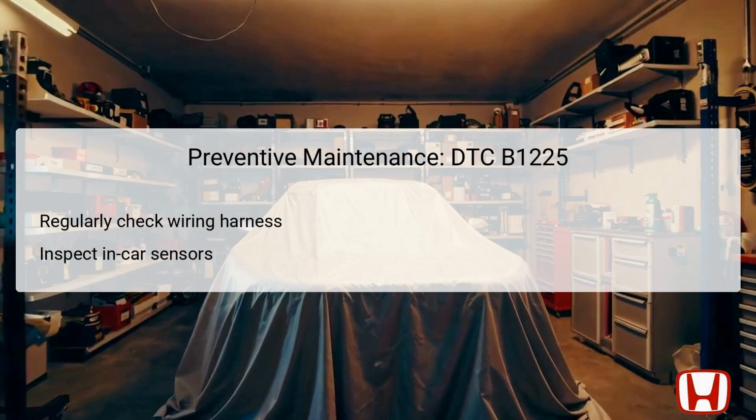Preventive maintenance plays a vital role in avoiding recurrence of issues, such as those associated with DTC B1225. Regularly checking the wiring harness surrounding the in-car temperature sensor can help prevent future problems caused by frayed or disconnected wires. Technicians should inspect these wires for any visible signs of wear, damage, or looseness, as they can significantly impact the system's functionality. Additionally, periodic inspections of the in-car temperature sensor itself can identify any early signs of malfunction.